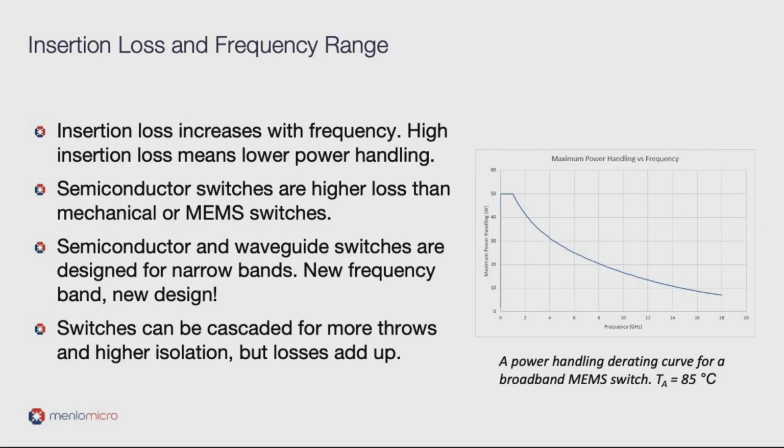Talking about the different switch technologies, the semiconductor switches will typically have higher losses than mechanical or MEMS switches. Another consideration will be that semiconductor and waveguide switches are designed for narrow bands. Even if this meets the band requirements for your application, a new design in a new frequency band will require a new switch design. This is why using broadband switches can often save on design time.